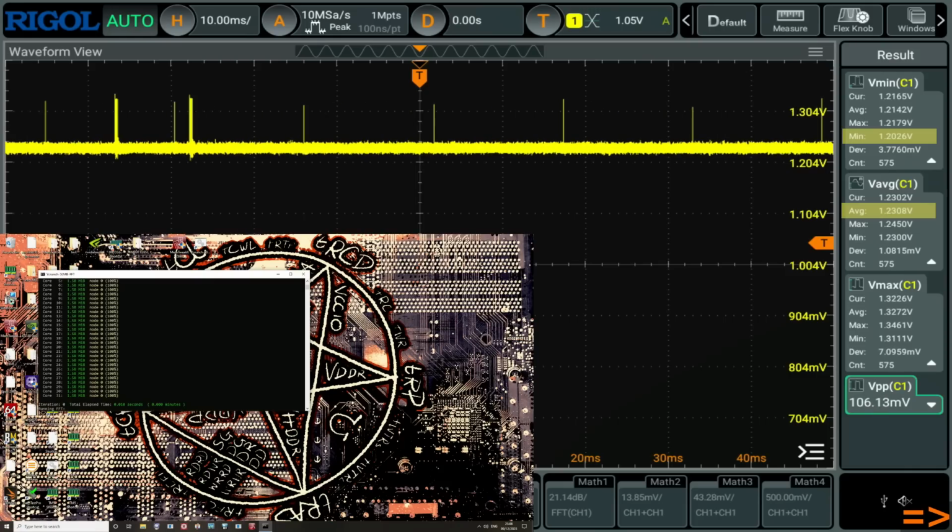But yeah, this is very solid voltage regulation at this point, and I think with a lower core count CPU like a 13600K, mode 7 would actually be extremely usable. Maybe even on a 13700K. Maybe if you ditch the E-cores, it would also be very, very usable. So yeah, mode 7 is actually pretty good. It's not perfect. We can still see undershoot in the waveform, right? And if I'm not touching the mouse, we're seeing a minimum of like 1.215.